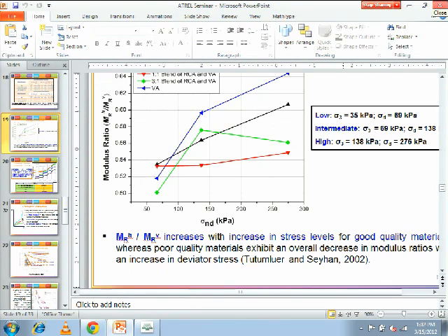How about if we threw RAP in there? What would happen? Permanent deformation will be high, very high. So you don't recommend that? Well, permanent deformation will be high. How about the modulus? Modulus will also be high. Because that seems like a possibility, to use RAP as a subbase. People have done that. I'm just curious how it would, my guess is I would agree with what you said.